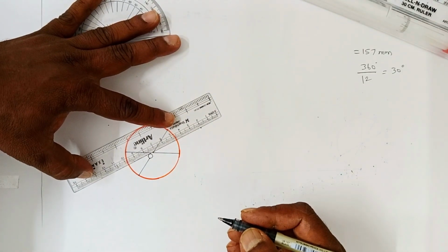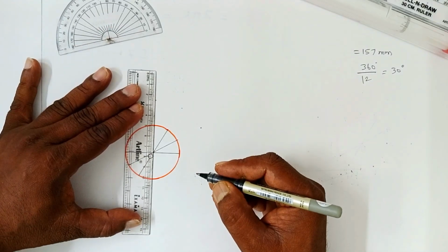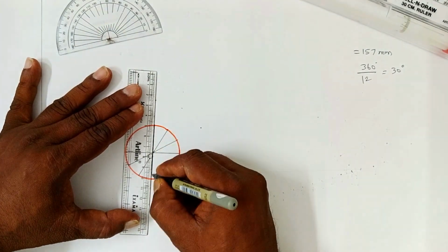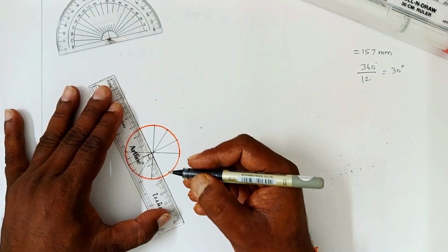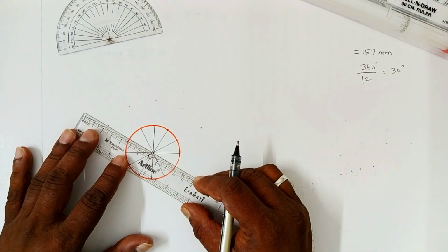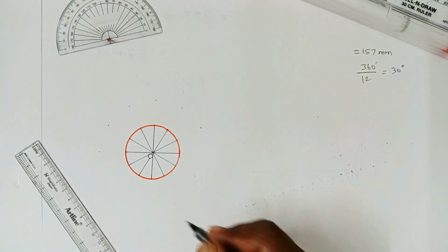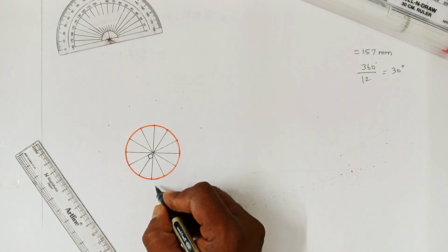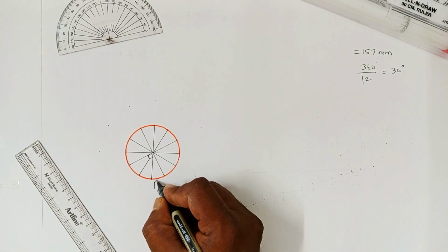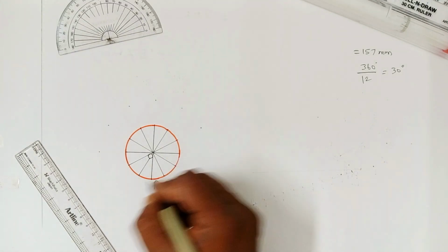So now I am dividing the circle into 12 equal parts by this procedure. The lines shall be drawn using a 2H pencil. It's all construction lines, so they will be lighter. This will be the base point marked as P for drawing the involute. This will be the P point. Then you give numbers to the divisions obtained.